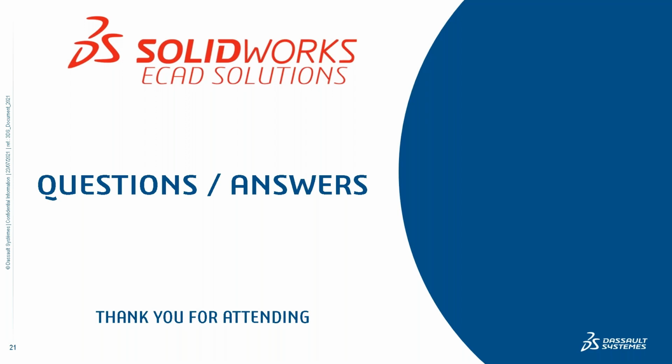All right, so that was one question. Another question was, what is a cut list, Thomas? Go ahead, that's an easy one for you. Okay, yeah. A cut list is essentially the wire information: where it's going to, where it's coming from, and length information for that segment. So at each segment we know the to, from, and length information, which produces a table that articulates the same. Wire run list, to-from wire list, they all kind of go hand in hand.